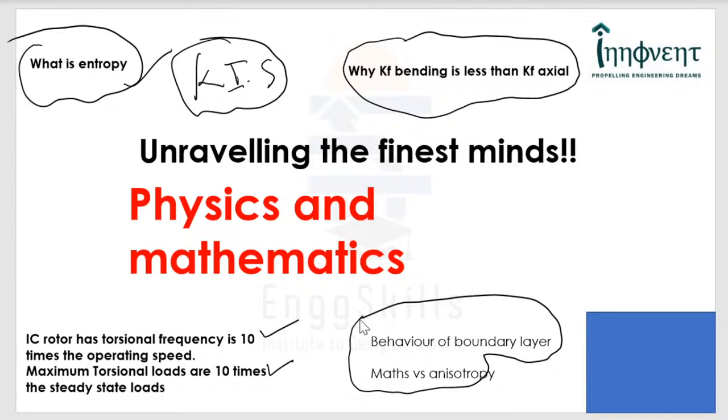And sometimes mathematical equations can be related to physical reality. For example, if somebody is from the CFD domain or fluids domain, or even a mechanical engineer would have pursued fluid mechanics, and if you consider one of the viscosity models, a d-viscosity model, and if you observe carefully, it is very clear that a strain tensor is related to a stress tensor by a scalar.